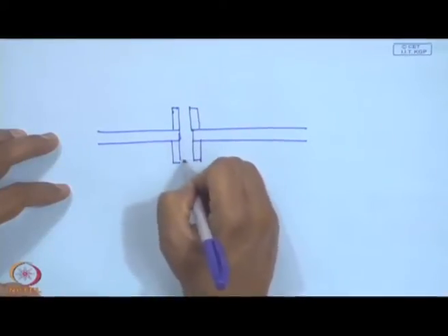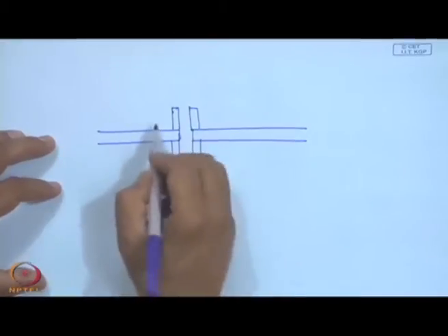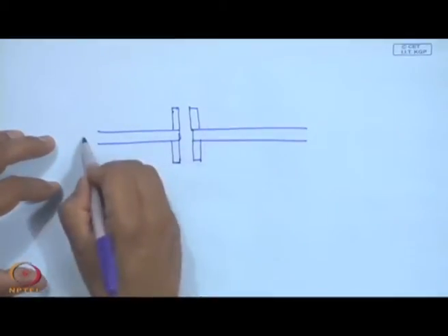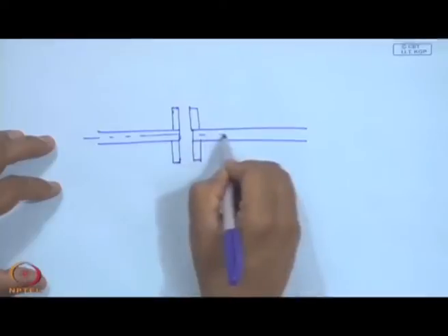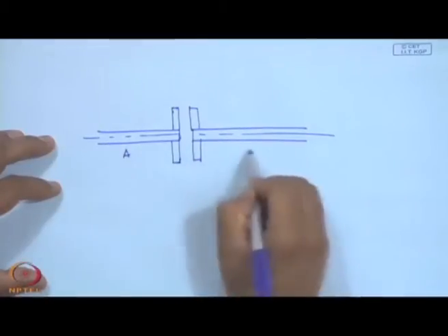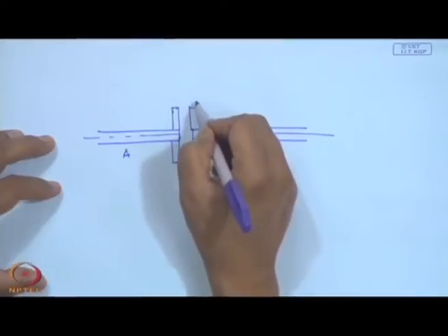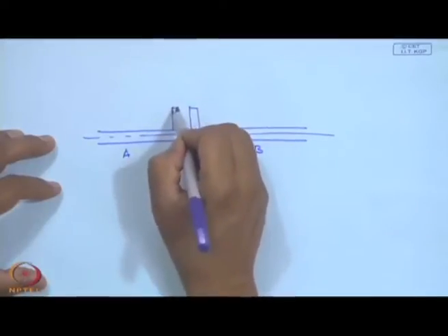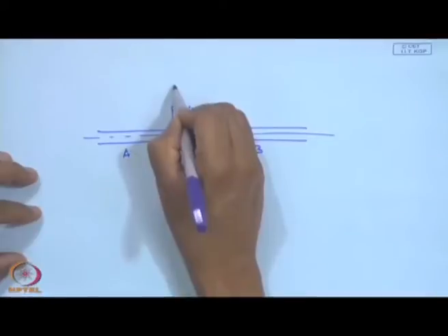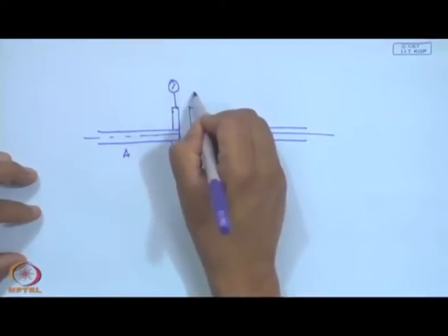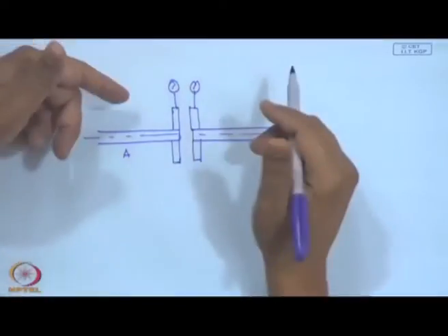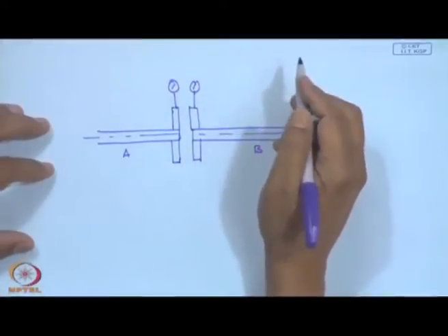If I was to align these 2 shafts A and B, whatever motion happens here is also going to happen here. So, I can see the dial gauge reading here and on this surface, and as I rotate it, they should all give the same reading.